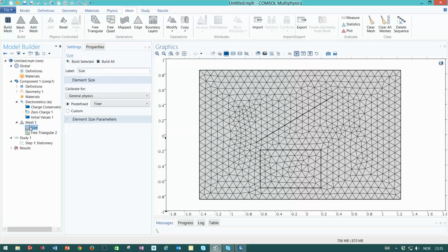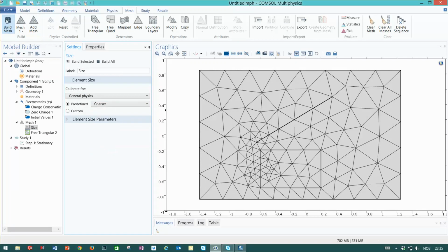And we can go in here and change the mesh in the same way as we did up here earlier. I can make it coarser, and then I get the mesh like that. Still, this is influencing how the mesh is generated. The program has a kind of energy and distance evaluation, and automatically it makes smaller elements down here than up here. It finds this to be a good solution, but really the program doesn't know, and the program is not very smart all the time. Very often it is.